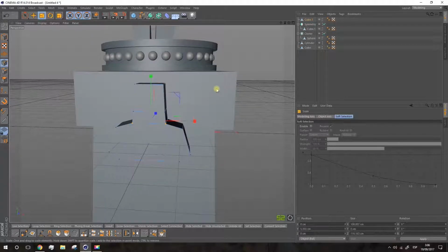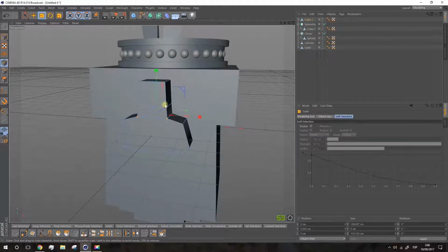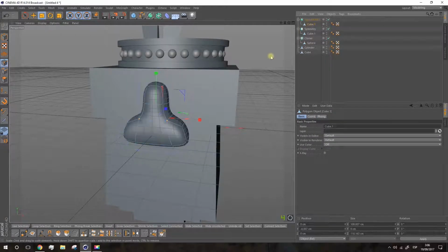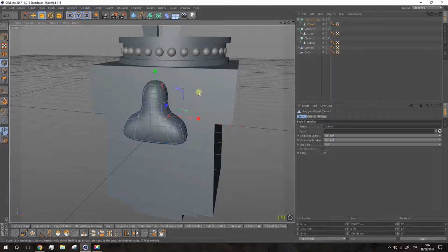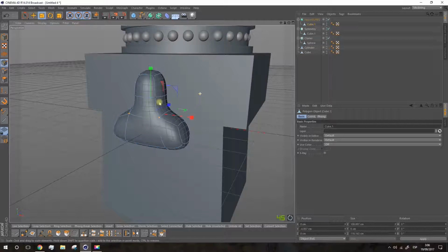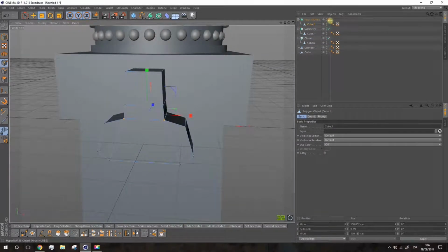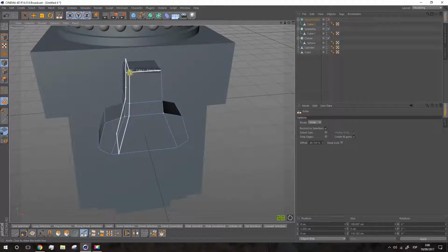Now we could do what we did in the first exercise, which was to apply a Hypernurbs. We don't want the nose to look so square, so boxy. So we can use the Hypernurbs to soften the edges. So as we saw when we made the banana, the edges have softened and the shape has become more organic. But we might not want it so organic. So let's just remove this Nurbs a moment. And we're going to make a few cuts. Okay, something like this.